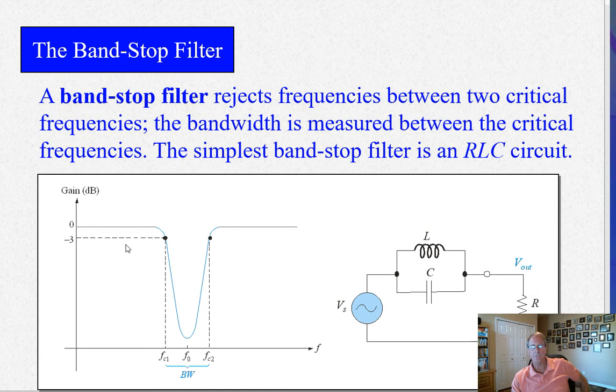Now, on either side of this, the same stuff happens, right? At low frequencies, what happens? The inductor is a very low impedance. It's a short, I mean, except for the winding resistance. So you get signal. Again, at high frequencies, the capacitor becomes a short, so you get signal going through. So it's all good. But at some point, both of these have some inductive or capacitive reactance, and you get less signal. So you get a voltage divider, basically, between this load resistor and whatever the impedance is of your parallel network here.